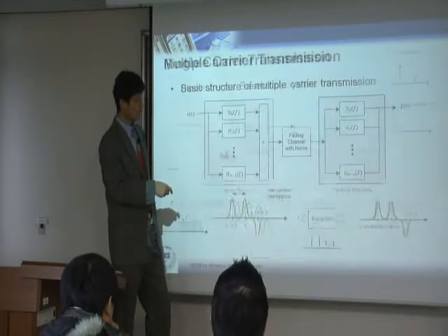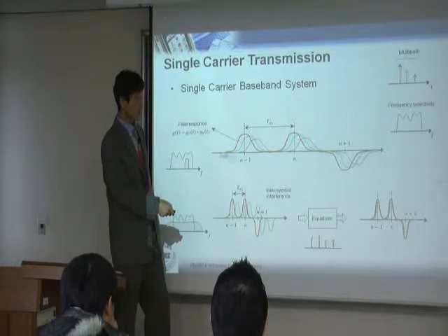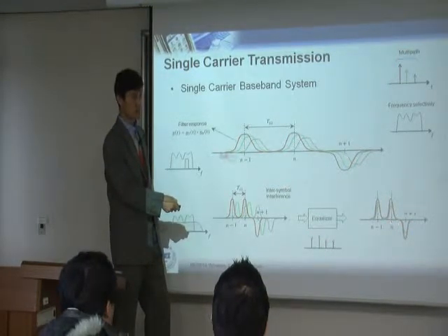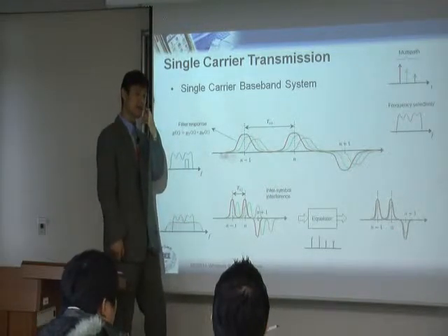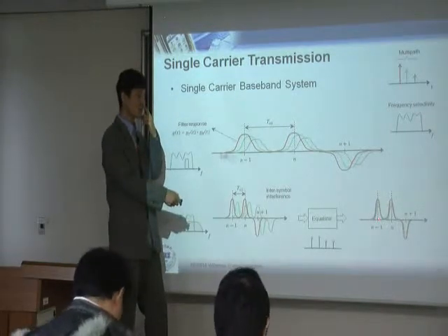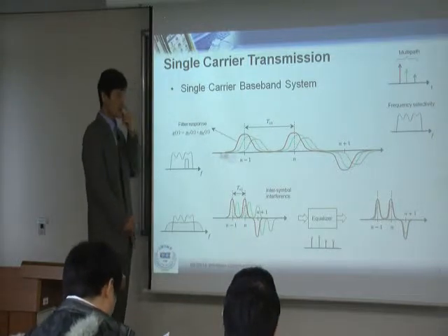Going back to the single carrier system, we need many taps in the equalizer. But even then, you still have remaining interference. This is a fundamental reason why your telephone modem earlier could not exceed 56 kbps, because of the remaining interference. That was a fundamental reason.